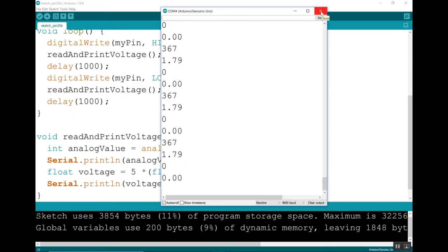All right, so now let's go back to the circuit, and I'm going to show you how we'll replace the LED with the temperature sensor, and then replace the resistor with just a bigger resistor, and then we get basically the same circuit, but with two different components. Then we'll come back and modify the code to see how we can use this analogRead to figure out what temperature is.